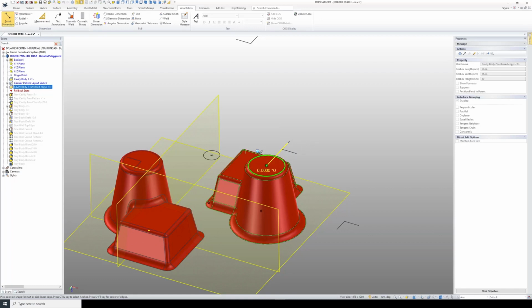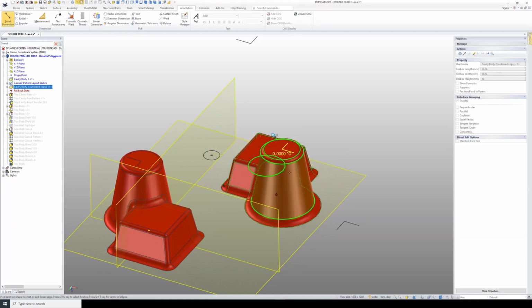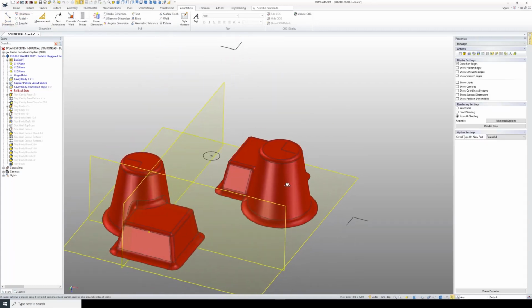And so select again the center of my body here and select this line. Now again, I don't want a point, I want to select this line here and right click to lock it and right click again to edit the value, and I'll put 0 and I'll deactivate the tool. So now this body is locked to my sketch using some dimensions.